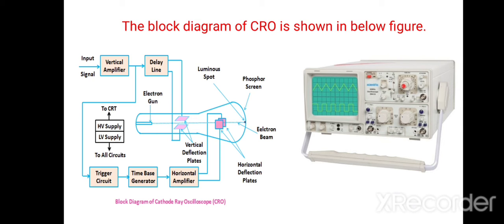Thus, a small delay occurs, and the signal reaches the vertical deflection plates before the horizontal plates. This causes distortion of the signal on the screen. To avoid this situation, a small amount of delay is added using the delay line block after the vertical amplifier. This is the main function here.